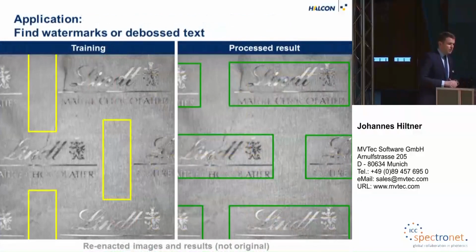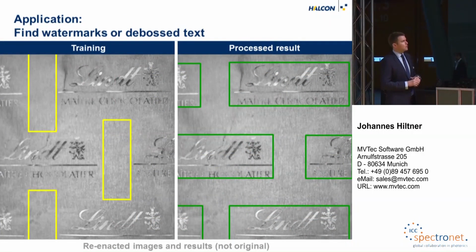And this is a pretty funny application which we solved the last couple of days. This is this aluminium foil from chocolates, from the Lindt chocolate. So on the left side, these yellow rectangles we used as training samples for our texture inspection model. And so the texture inspection model now knows how the background texture actually looks like, and all gray value changes within this background texture are now segmented as a defect class, so to say.